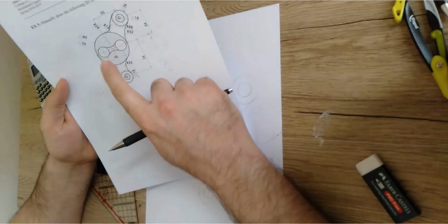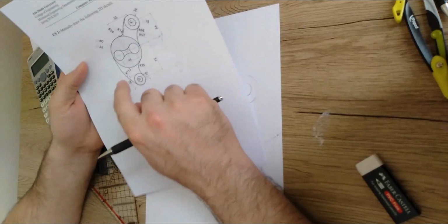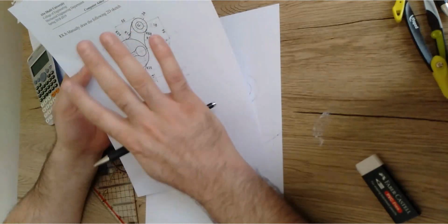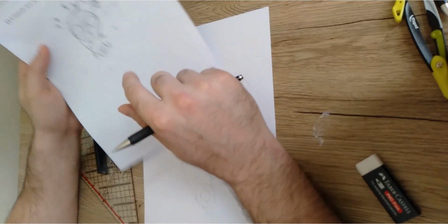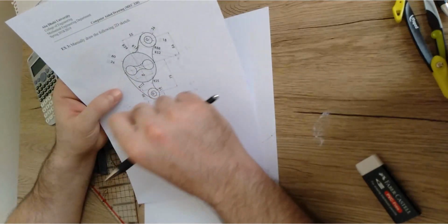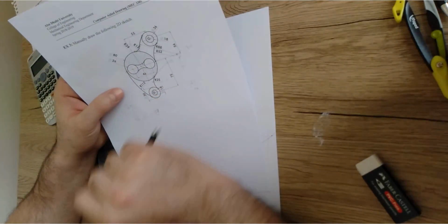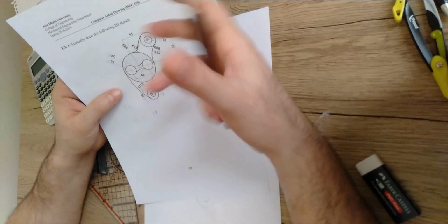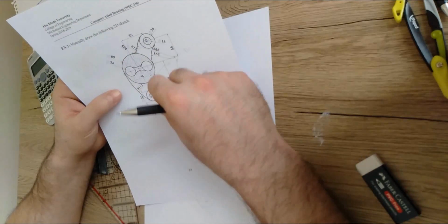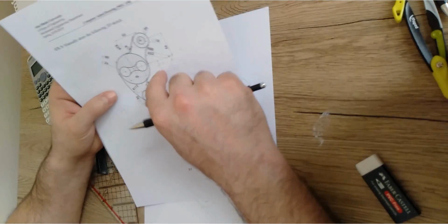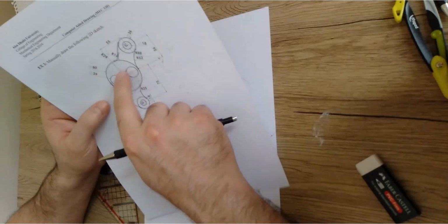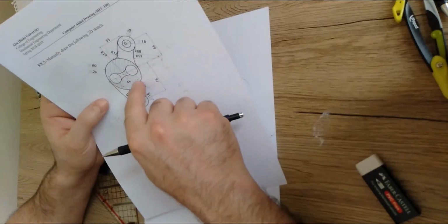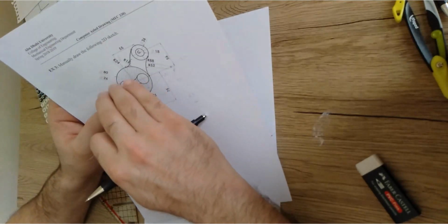But for the hatching, make sure it's the last thing that you add to the drawing, just before you finish, and make sure that you won't finish the hatching separately. You're just gonna do it once and that's it. It means that it should be neat and clean. And another thing, the spacings between the hatch lines should be identical. It means that the space between these lines should be fixed.